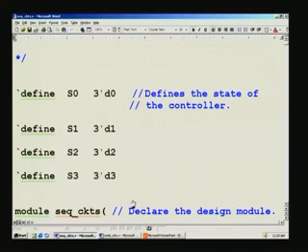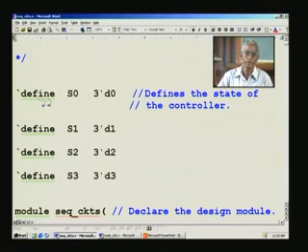And here there is another new thing which we have not seen before. There is a tick here followed by define. This is to define variables, suppose you have a variable, then you can define it. You also have another counterpart called parameter. We will not deal with it right now, probably we will see it later on.